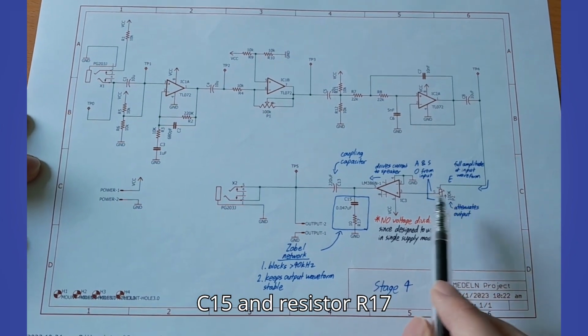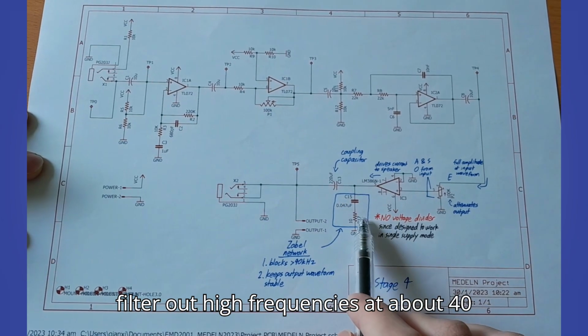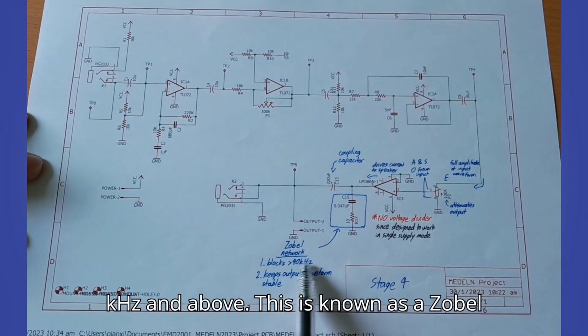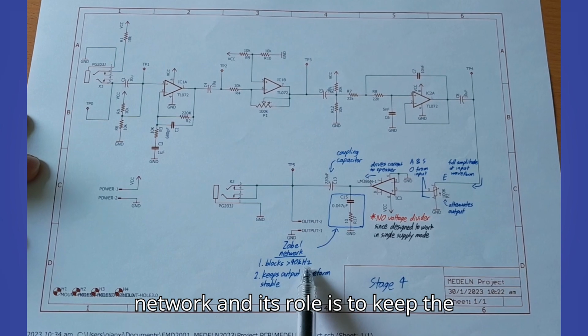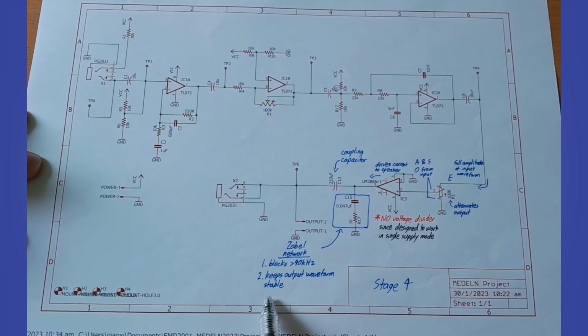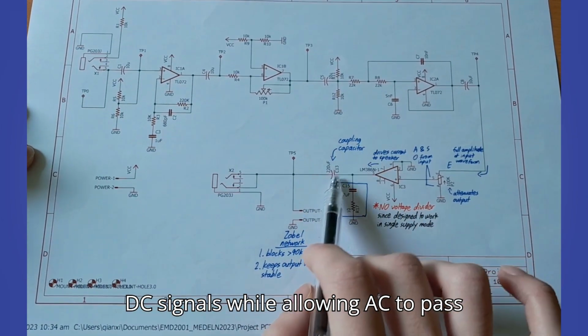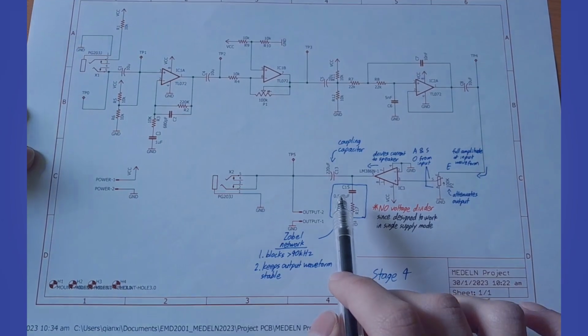Capacitor C15 and resistor R17 filter out high frequencies at about 40 kHz and above. This is known as a Zobel network, and its role is to keep the output waveform stable. Once again, C13 is a capacitor that will block out DC signals while allowing AC to pass through.